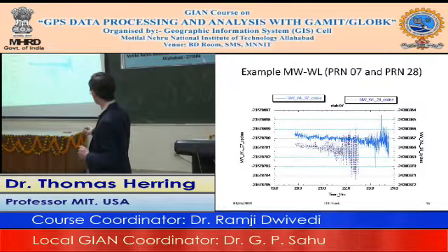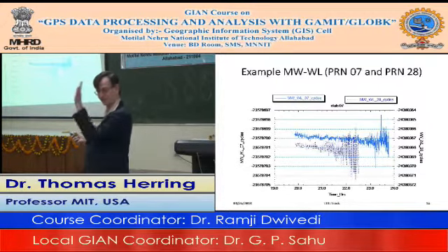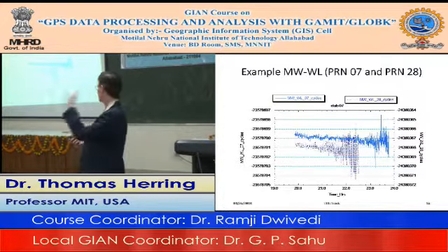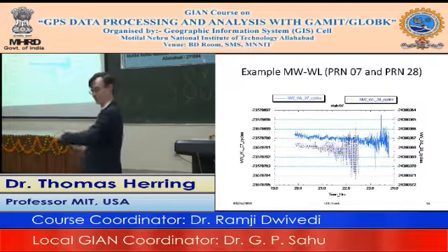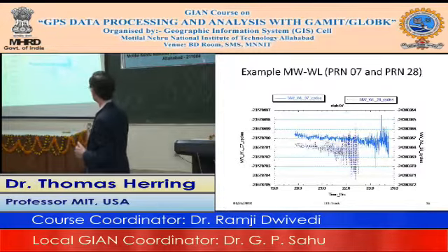Notice also, these satellites are setting. And so as they start setting, you just get much, much more noise in the range. We saw that in the elevation angle dependence in the phase residuals. You saw it in the multipath range plots yesterday. That's a common characteristic. The lower the elevation, the more noise. So this is more difficult to do when you're down in this part.